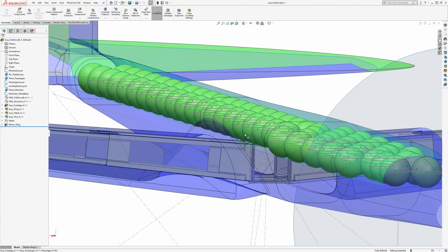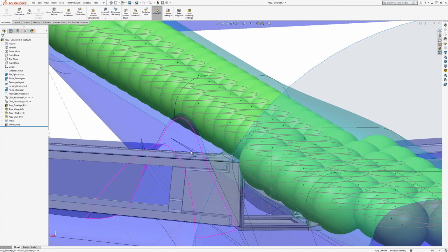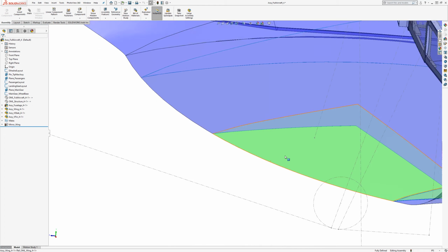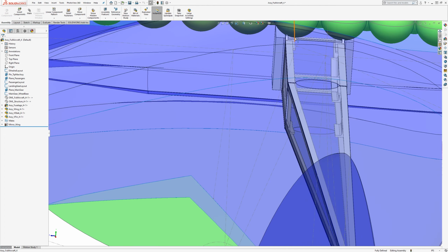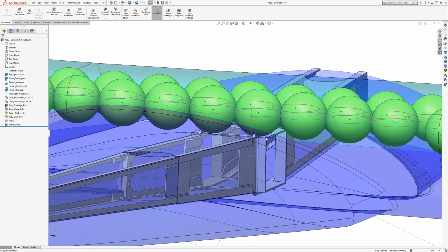So that's what I'm going to do, is going to raise this whole beam up and then curve the wing top skin up and over the top, and have a sort of a beefy frame that has a cutout for all the passengers to have sort of a tunnel that they exist in for that 4 inches of fuselage stations here.